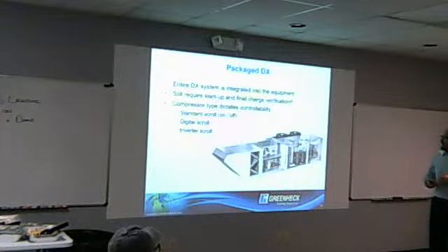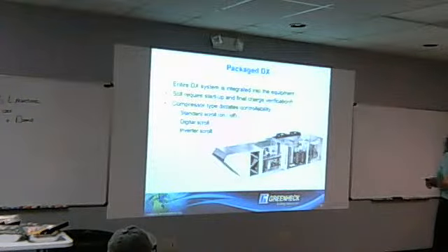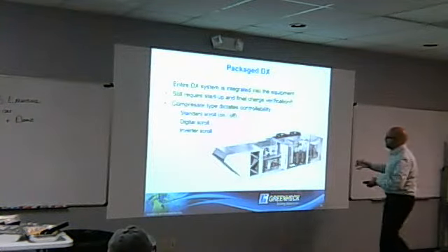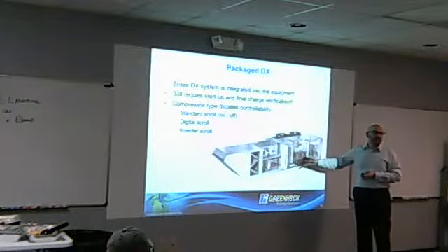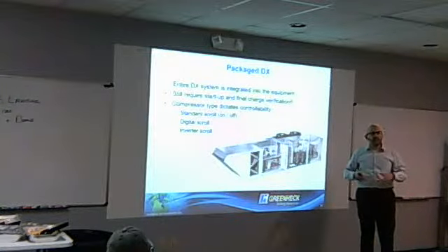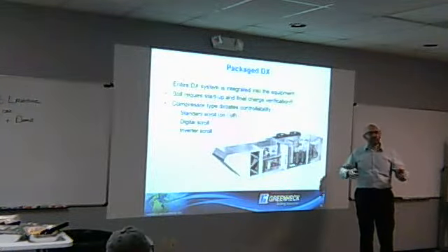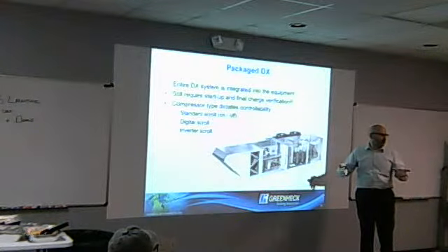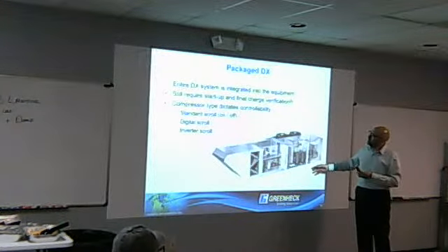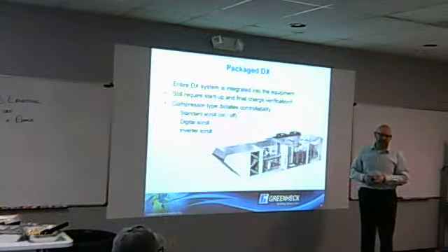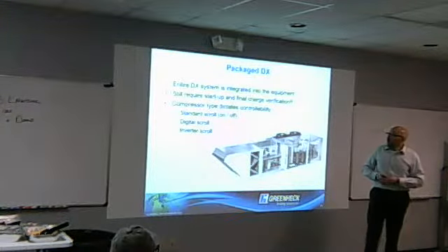In the package DX, obviously it's fully integrated, you're familiar with that. The final charge and startup: it comes to a unit with a pre-charge, but we don't fill it all the way. So there is a comment saying you've got to start this unit up, you've got to verify the charge. You might have to prime it or add a little more to it to get to where we need to be. Standard scrolls, I don't see those used very often anymore.